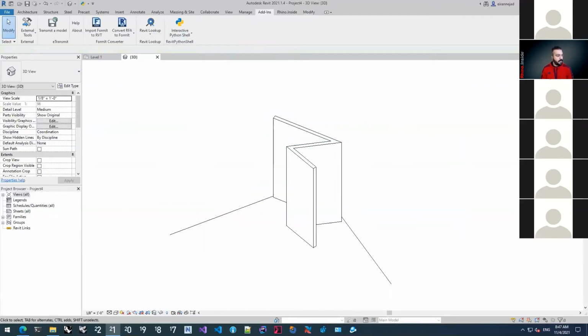We want to talk about a couple of things that are super important when working with the Revit API. First of all, the Revit API has two different major sections. One is the one that works with the Revit content, the content of your model as a database. That's called DB. And the rest is called UI, and it works with everything that's related to the Revit UI. So if I want to add a button to the Revit UI in my add-in, I'll use the UI API. If I want to work with the walls and the contents and all that kind of stuff, I use the DB namespace that's related to the database.